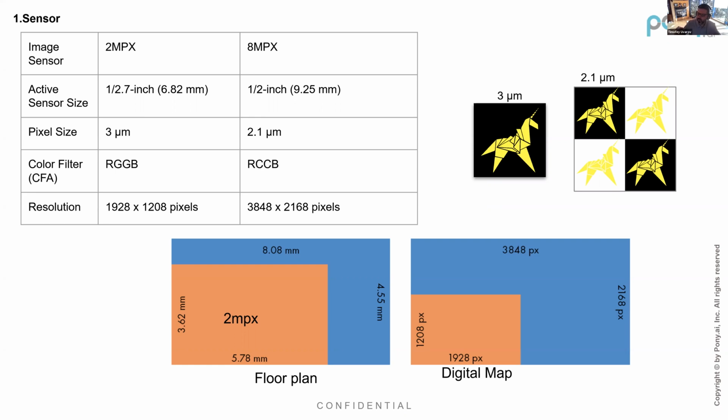If we bin 8 megapixel by 2, it will have a big pixel which will give us higher dynamic range and maybe better SNR, not sure, depending on your exposure settings. But it will definitely reduce the resolution, because for the same area we will have far fewer pixels, and we will go below the original.